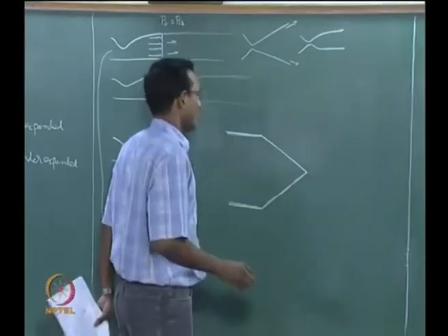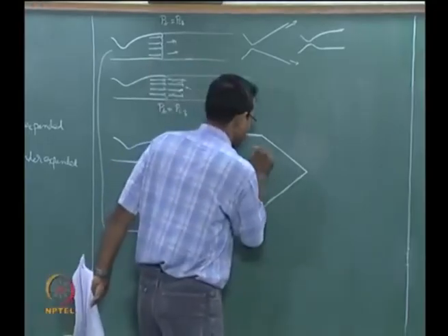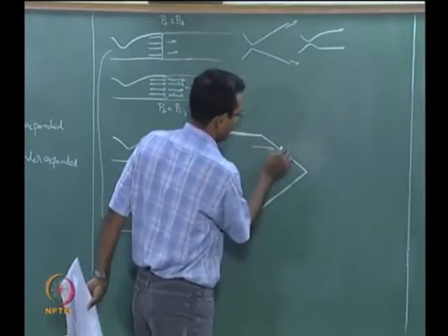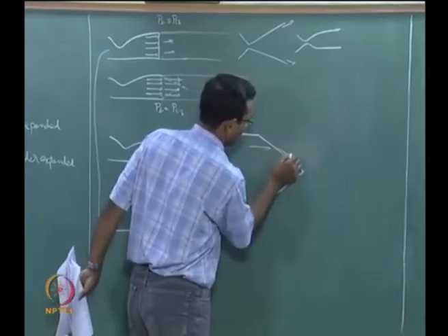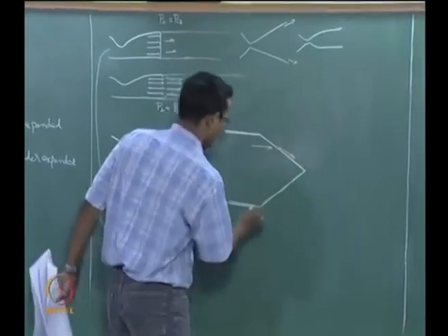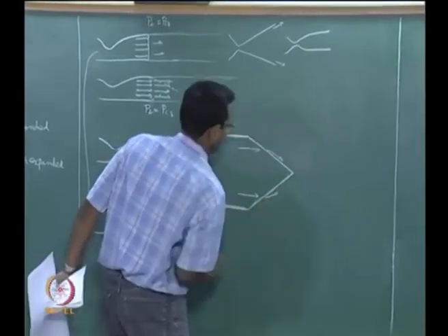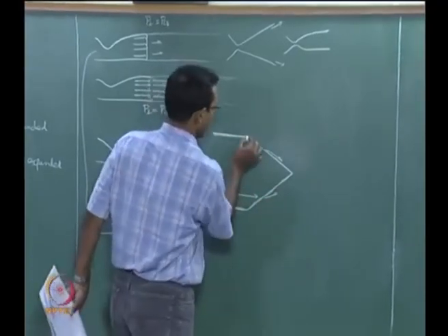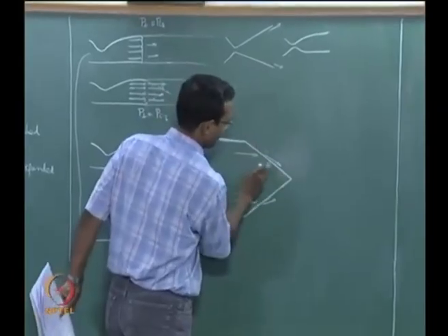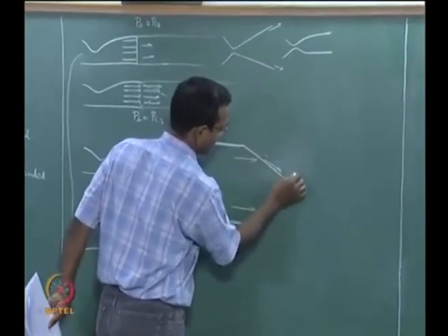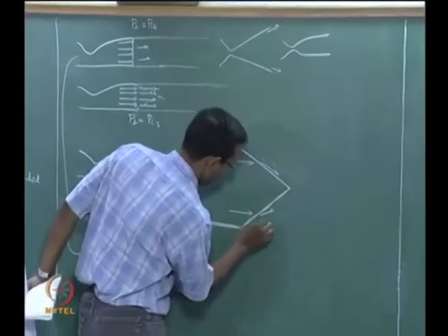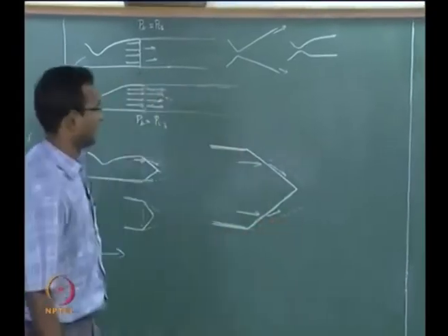Okay. Now, a fluid element here is coming at this angle and because of the oblique shock it is turning like this. Same thing here. And so, my jet boundary is going to be parallel to these post shock vectors, something like this.